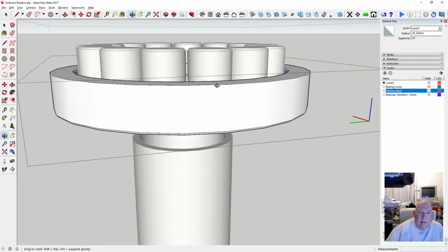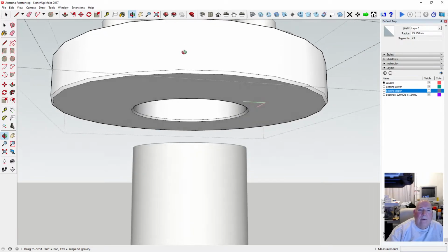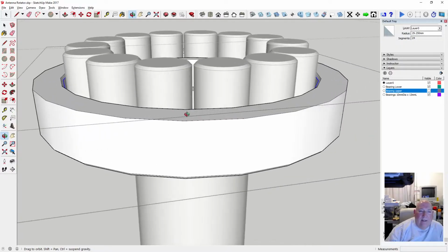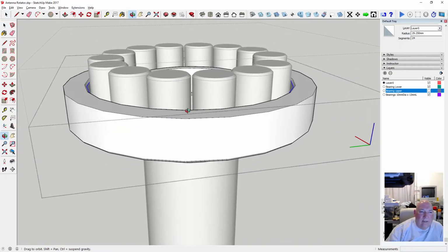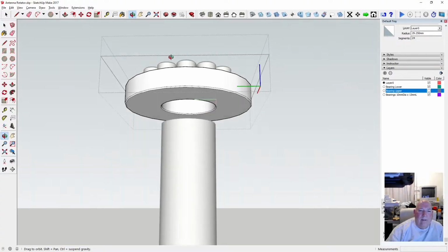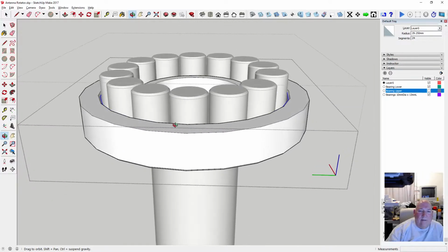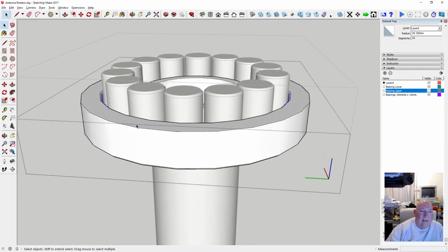Yeah. So we need to do an overlap as well, to stop the water getting in. So we're not going to use a seal, we're just going to overlap it, let gravity do the work. Yeah, so we'll have to make these unique. So I need a recess on this one.